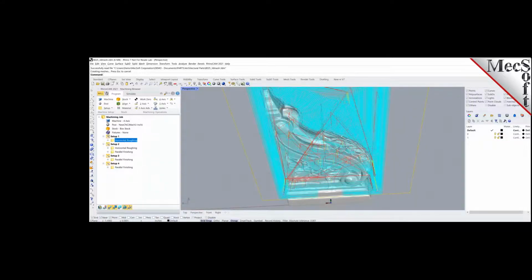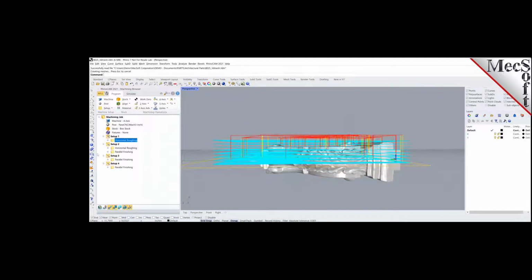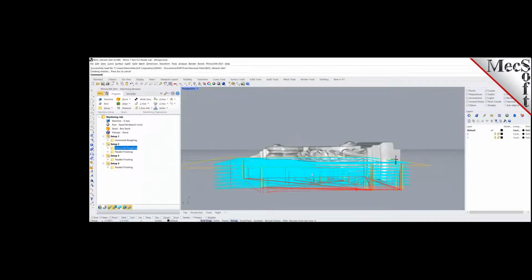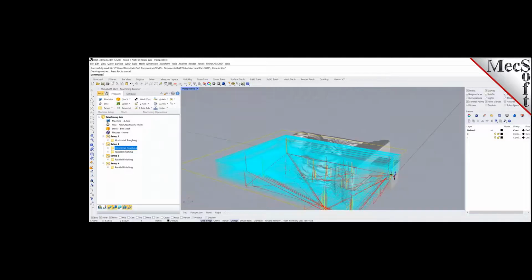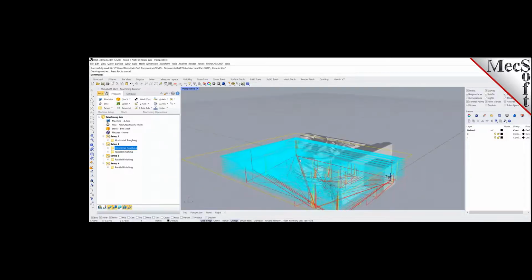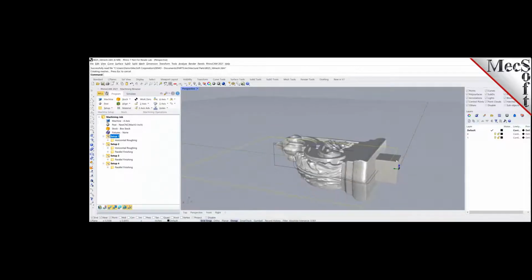We've done a roughing on one side, on the top, and a roughing on the bottom. So this will work perfectly with your 4-axis machine. I think this customer is using a 4-axis, that's why he's got a block sitting here. You can anchor it to a 4-axis head, rotate the machine the top, then flip it over and machine the bottom, then do a finishing on that, and come back again and do the finishing on top.